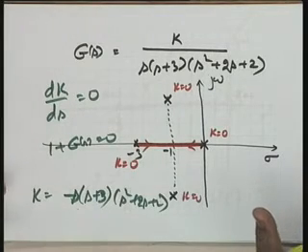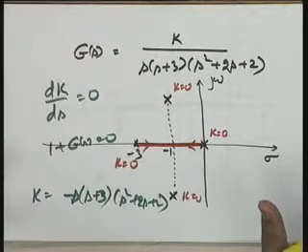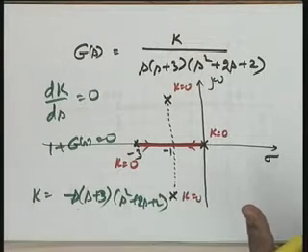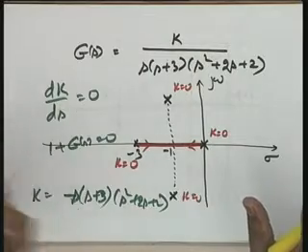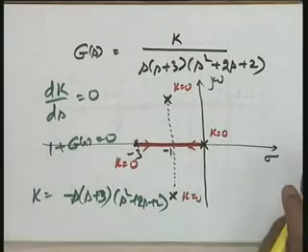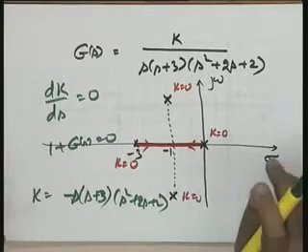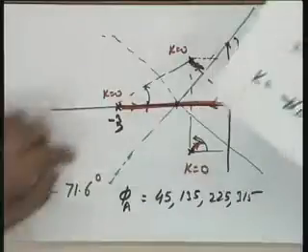However, if you are sitting at the computer terminal, you will immediately check for the other breakaway points. But if you are doing it by hand calculations, then this guideline is good enough: you try for one real root of the equation, and you roughly know that the location of the real root should be somewhere in this particular region, and hence the breakaway point can be calculated.